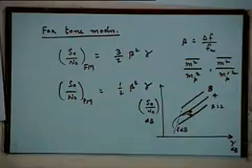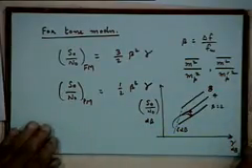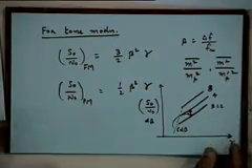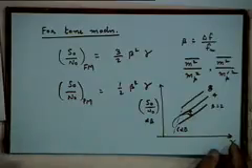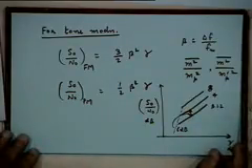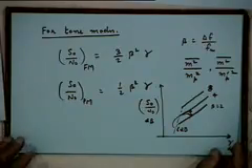Right? That kind of effect will occur much more pronounced now than it was for the case of the envelope detector in the case of AM. So the threshold effect phenomenon is a very important phenomenon in the context of angular modulation. It is not so important in the context of amplitude modulation. If you remember, I discussed this issue earlier. For the case of amplitude modulation, it is hardly relevant. Theoretically, it is there, but practically it is of hardly any significance. But for the case of FM, angular modulation, it is of great significance. So we look at the threshold effect in angular modulation now.